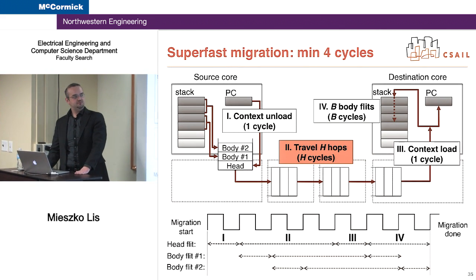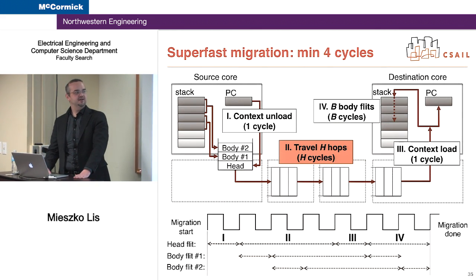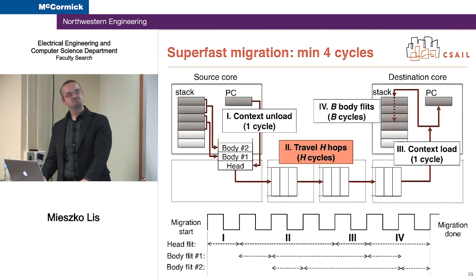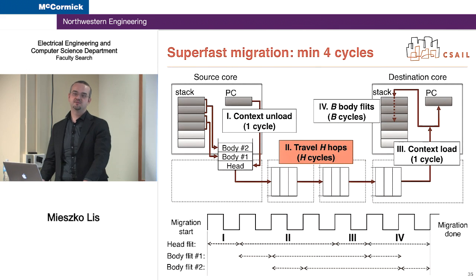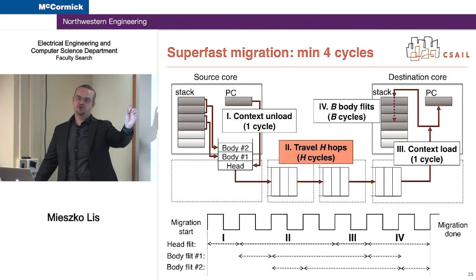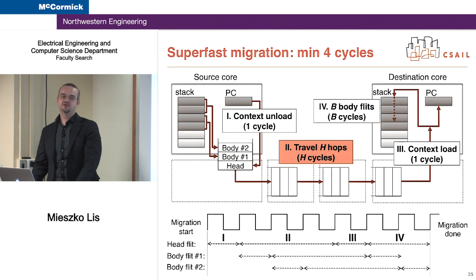But in general, you can get away with a slightly larger iCache. I would not expect to need 110 times the instruction cache, because of this effect, where the instructions that operate on a specific piece of data tend to go where that data is. The first time around you have a miss, but the next time you go there and execute the same piece of code, you hit just like in your regular cache.